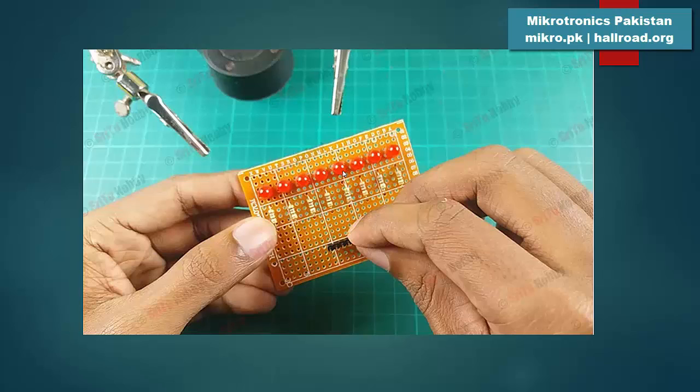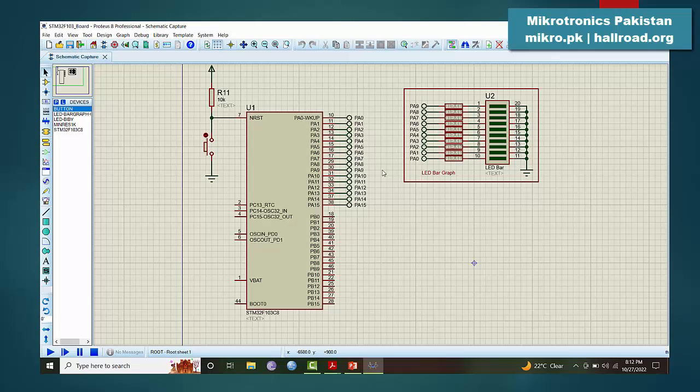It is also advisable that you have these small homemade breakout boards, like these, with 8 LEDs connected through current limiting resistors and a header, so that you can attach your microcontroller pins using jumpers and see the GPIO pins as output signals on the LEDs.